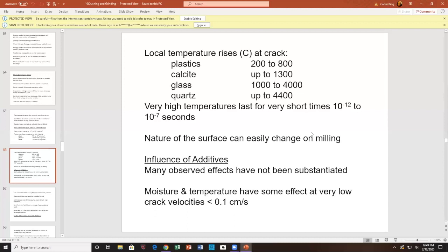You should also recognize that tumbling in a ball mill can be a generation of static charge. And it can sit there and crush and grind away on your material and be sparking all the time. So sparks and dust don't go well together. So you could have a ball mill generating dust explosions, simultaneously being ignited by sparks generated by electrostatics during tumbling. If any of you hear this and actually have this happen, it'd be fascinating to take some videos of that.